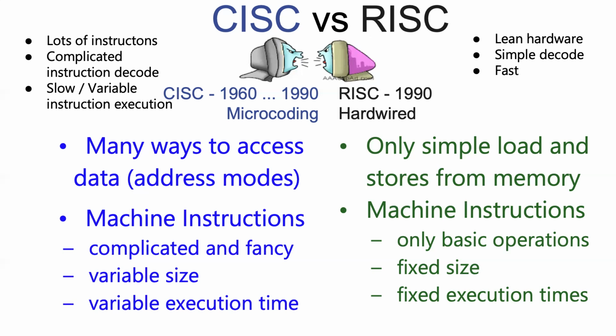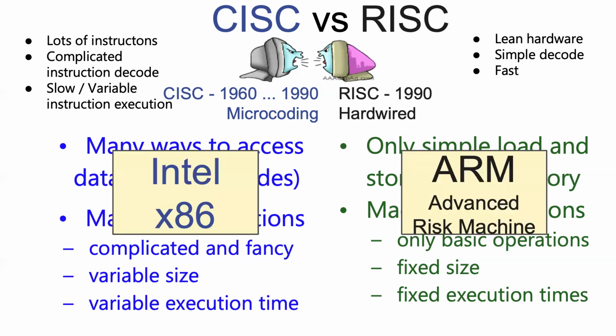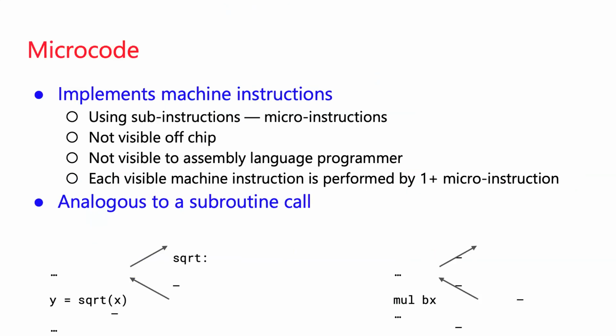So on a RISC model, I've said it a couple of times, we're going to try to get by with as few instructions as we can design. And by having fewer instructions that the processor needs to support, maybe it can do a better job of implementing those instructions more efficiently. I already said this a couple of slides ago. You probably don't need to be told. The 8086 is typical of a CISC design, and ARM that we just learned about is typical of a RISC design.